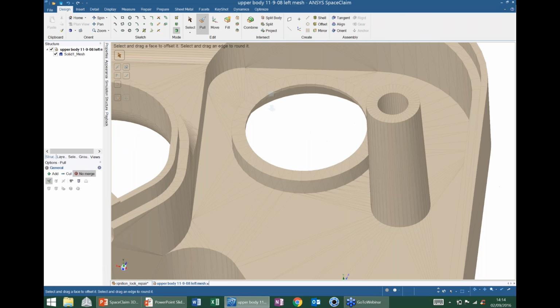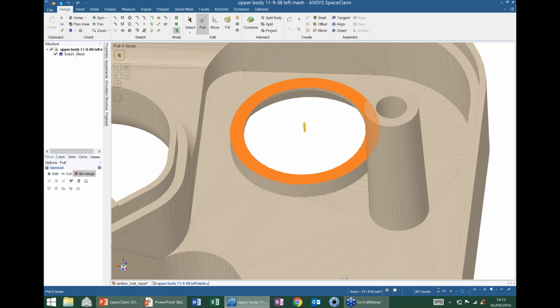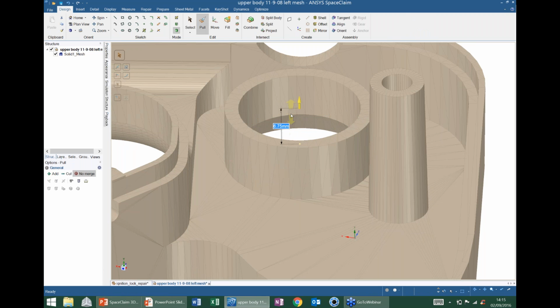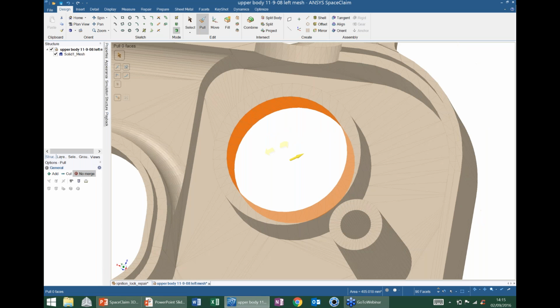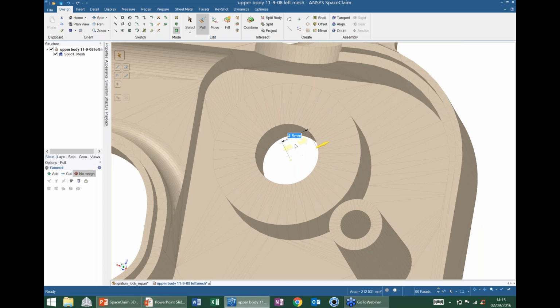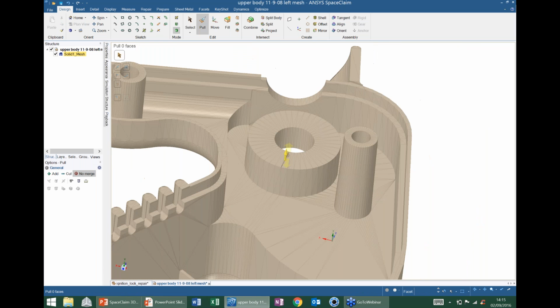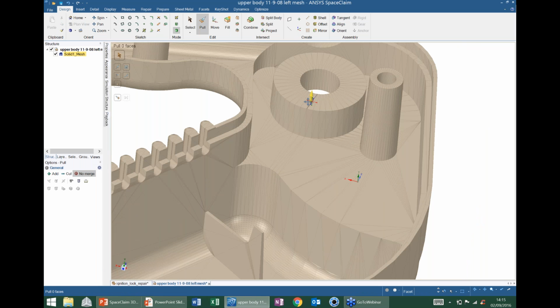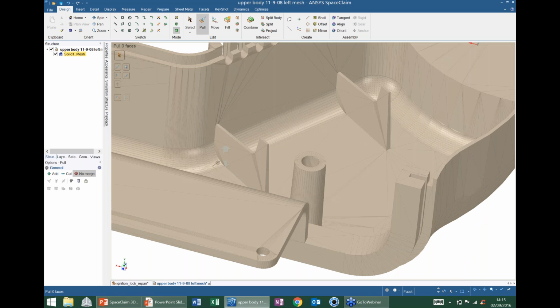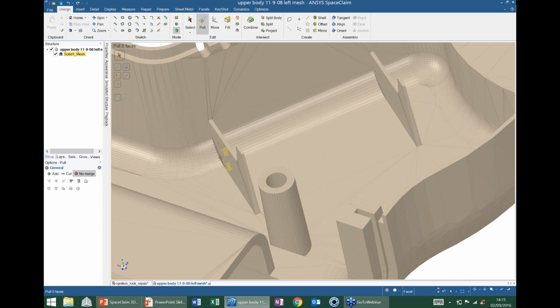So if I double click onto any of the triangles here, I can pull them up and you can give more thickness or reduce the thickness of any feature. If I double click on the inside, you can do the same here as well. So you can really easily edit an STL file, which other CAD platforms can really struggle with. I can come down here and maybe these parts here you think, I need to thicken these up, they're a bit too thin, so I pull this out.